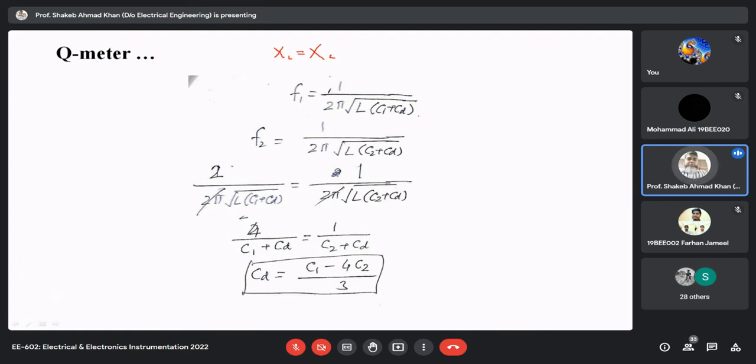So from this, obviously this distribution capacitance, although it is not a real, physical capacitance, is basically a stray capacitance, you can say. So this will be the issue. It will affect the value of the tuning capacitance.